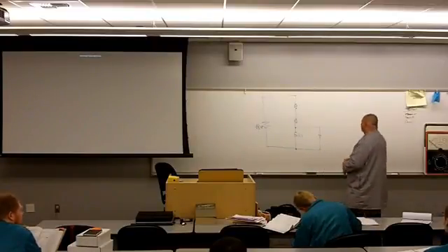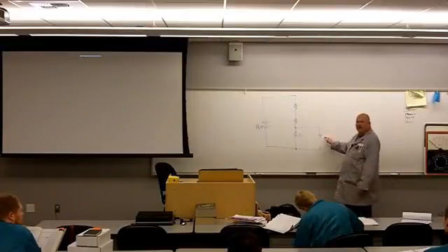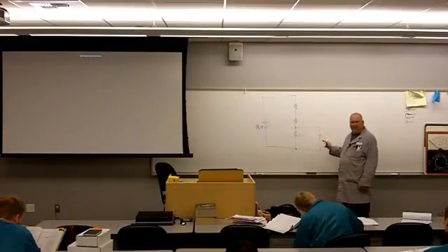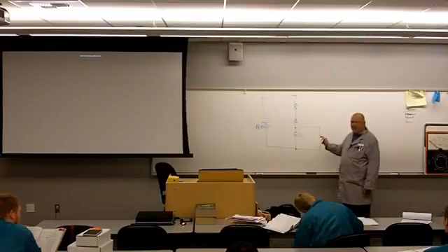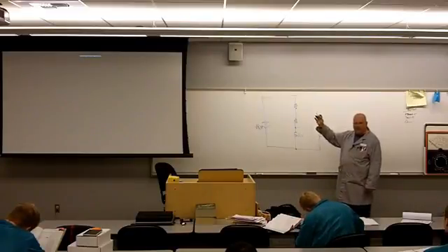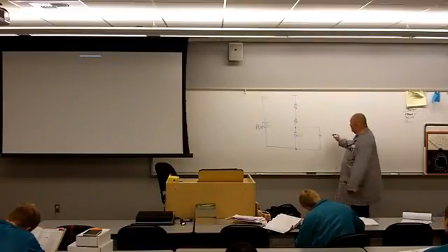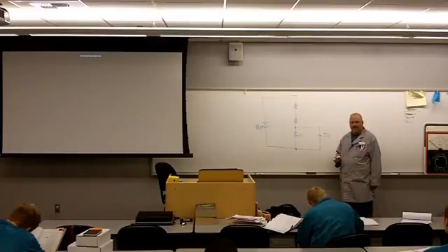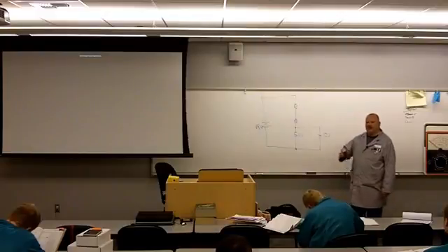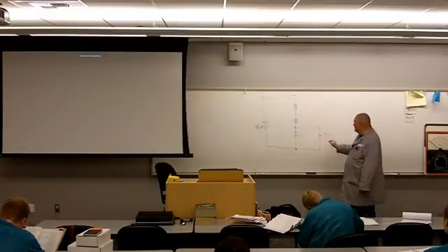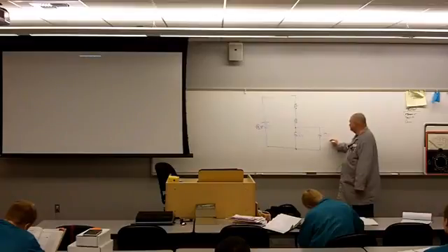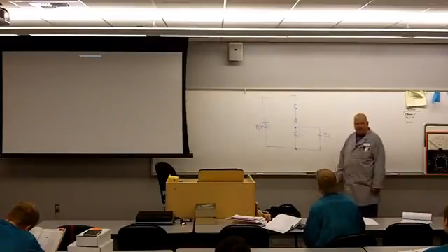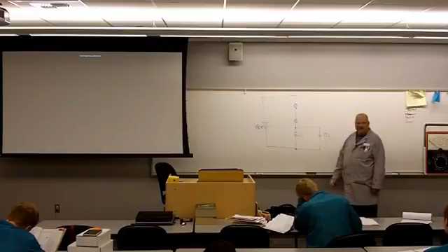So we know that this is 12 volts because the manufacturer said this is a 12 volt CB radio. You could plug it in your cigarette lighter, you could wire it into your car, and you too could be breaker 19. Make sense? So we know the voltage is going to be 12 volts. The other piece of information that is critical for us is we have to know how much current is required by the CB radio to operate properly.